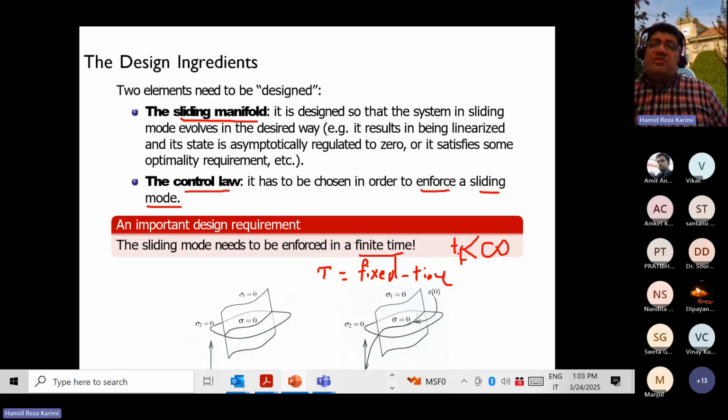A sliding mode just presents the finite time. If you want to bring it to the fixed time, we need to look at how to modify the control strategy to satisfy this point. But this is another research topic. Just another keyword you might be interested in is the difference between finite time and fixed time. SMC can only prove finite time, but SMC cannot guarantee fixed time. If you want to reach fixed time, you need to modify your design.